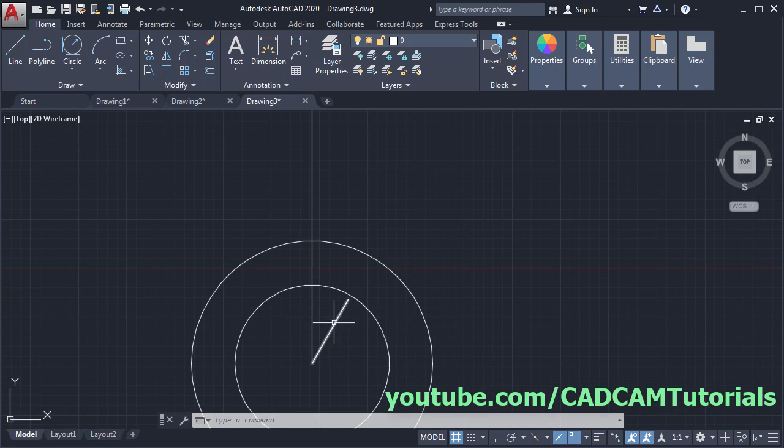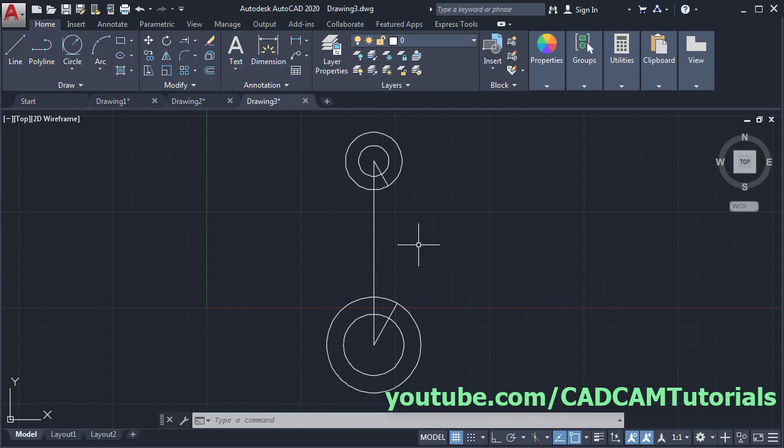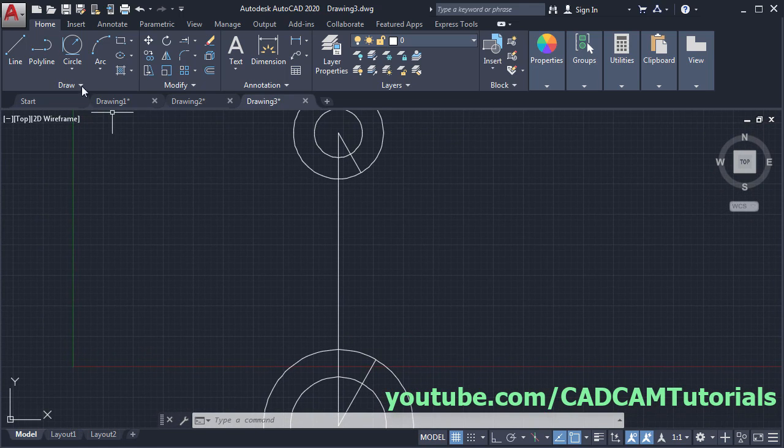Then we need to extend it up to this circle. For that click here and select extend, press enter, click on this line and again click on this line, press enter. So reference lines are ready. Then click on line, click on this end point and this end point and press enter.